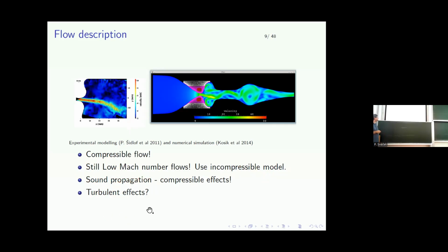Furthermore, I would like to mention that some turbulence effect needs to be included, more or less when the jet, which is formed by the constriction here, enters the fluid domain, which causes rotation of lots of vortices. So possibly turbulence needs to be modeled, but the application of a turbulence model is challenging here, because in the subglottal part, which is this one, the flow is mostly laminar, or maybe a turbulent layer is developed. But as the jet enters the domain, lots of vortices are created. So the application of standard engineering techniques like RANS models, Reynolds-averaged Navier-Stokes based models, is not suitable.